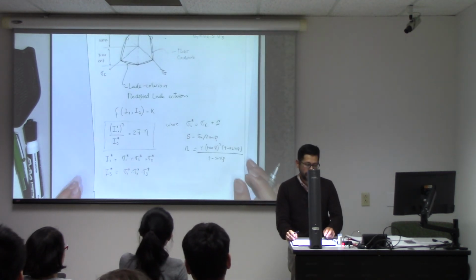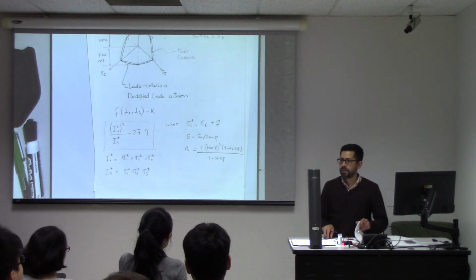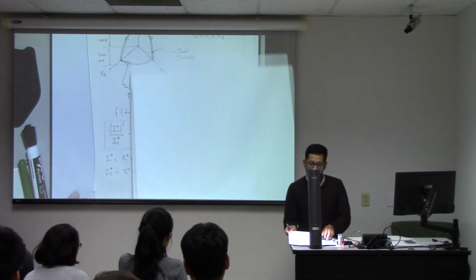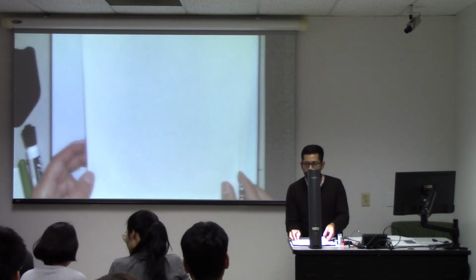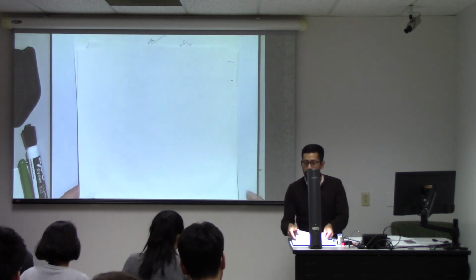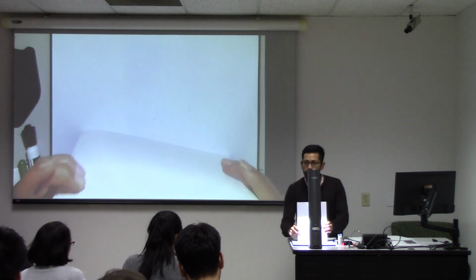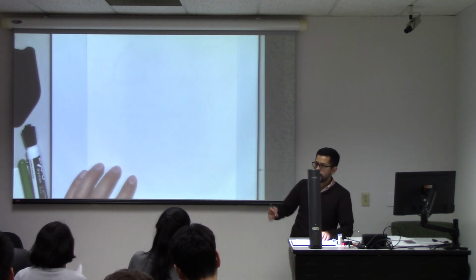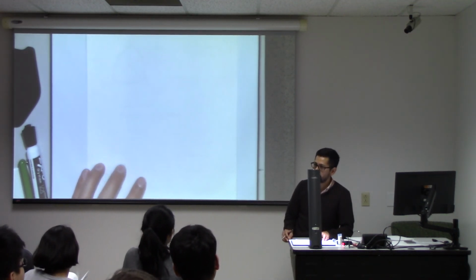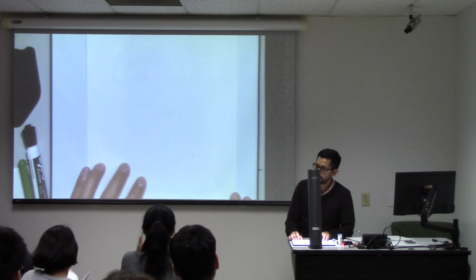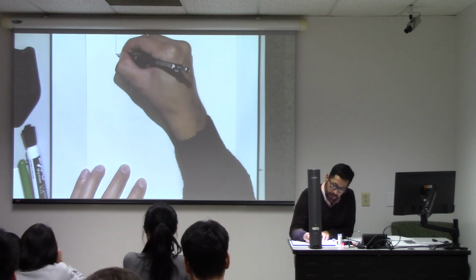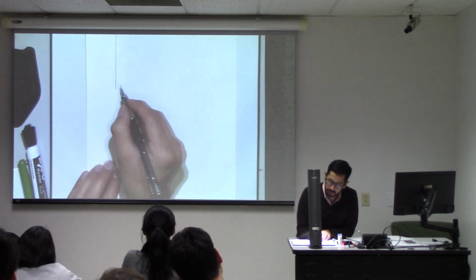And one of them is tensile strength. We didn't talk much about tensile strength. The thing is, tensile strength is just very easy. It's just one value. So as long as one of your principal stresses goes below that value, then you have a tensile failure. That's it. But we can summarize all of that into a single plot.